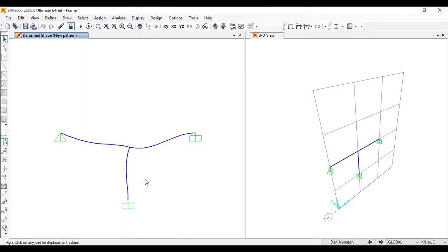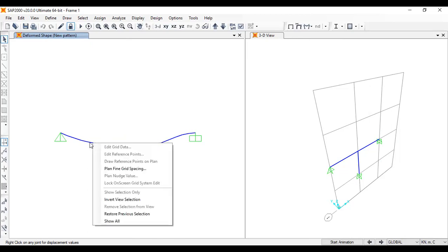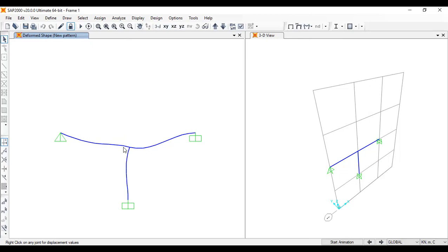So you can check the displacement. We only defined joints at these points, so it will only show the joint displacement for each of the 4 joints. It will not show at the intermediate points. Sometimes when you right click it, it shows, but not here. If you want to see displacement somewhere in the middle, you need to define a joint here, right? That means you have to divide the element into 2, right? Define a joint here, that's it, right? Because this structure is solved at these joints, right? So that's something to note in the name finite element, right?